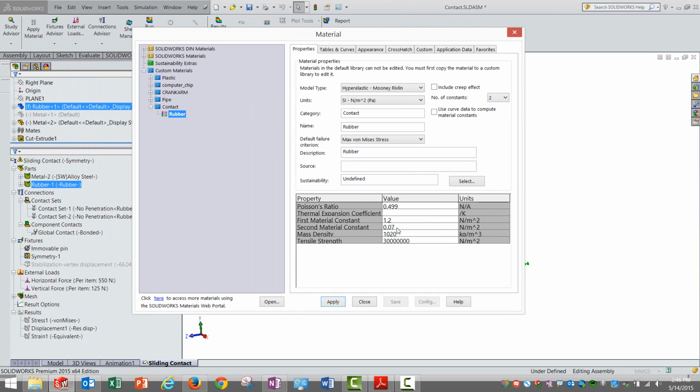In the last chapter, we saw that the software has the capability to convert a stress strain curve into Mooney-Rivlin constants. Typically, this is what is also called curve fitting, wherein we derive the constants, and then we can derive a curve out of the equations that these constants represent.